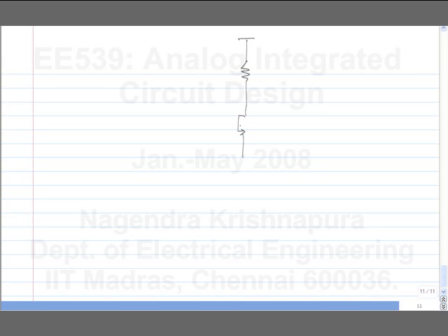Common source amplifier does amplify the difference, but here it is high impedance and here it is low impedance. And ideally, I would like to have high impedance in both the cases so that whatever source resistance I drive it with, the voltage is not affected by the source resistance. Okay. So what do I do to drive a low impedance case?